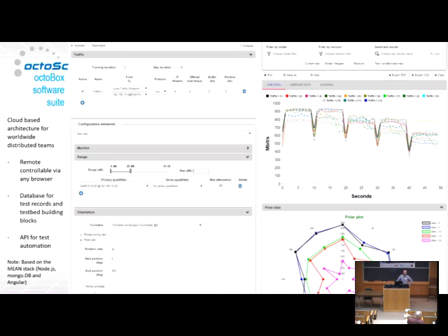What we can also do is incorporate statistical information from our PAL unit. So our PAL unit has the ability in its monitor mode to record signal strength information as well as the channel bandwidth of a Wi-Fi transmission or the MCS scheme that it's transmitted at. So we can include all of that in our plots, and then this can be saved and reviewed later.